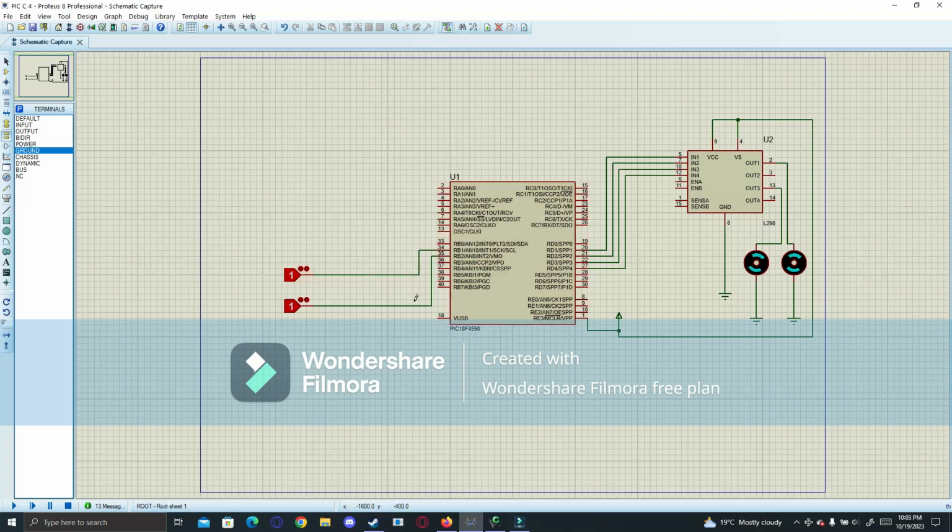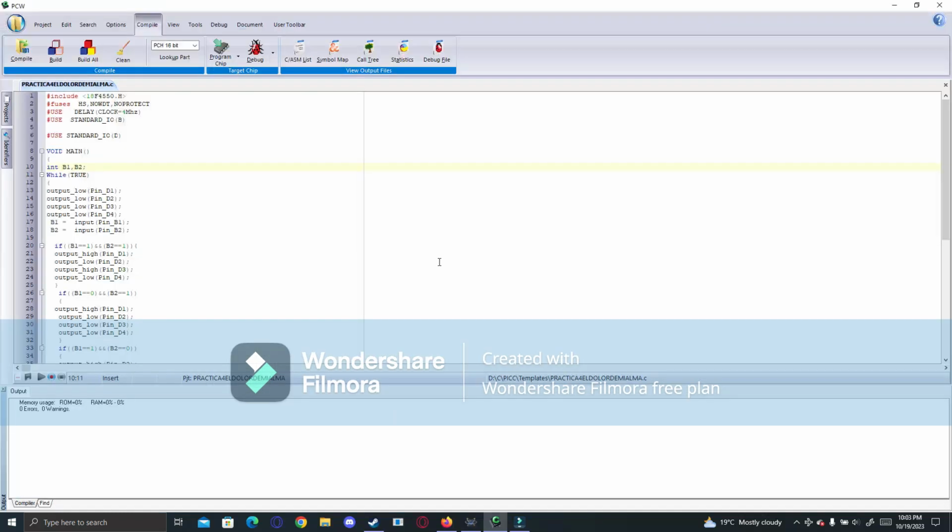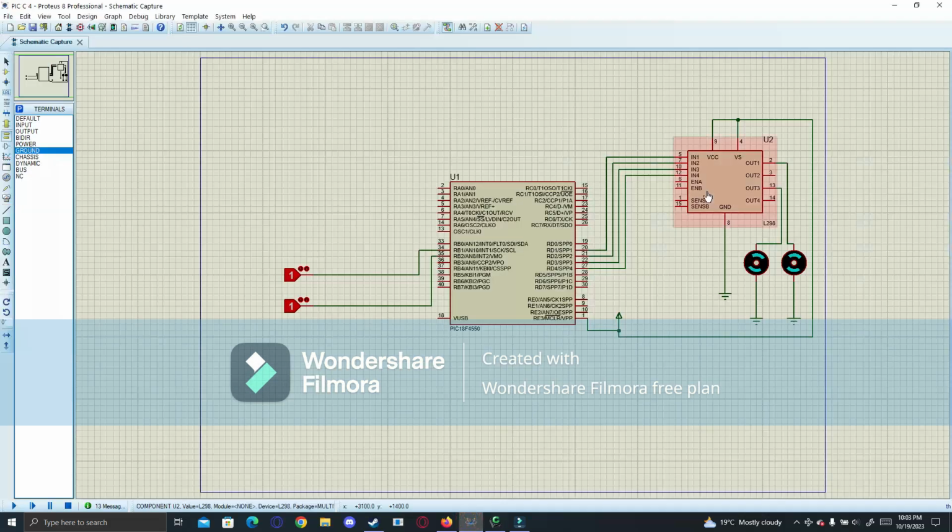The sensors will be connected to two parts of the car in the front, aligned with the motor that each is connected to. When both of the sensors are detecting no black tape, they are going to be sending a 1. This is the state they are going to be in regularly once there is no black tape, making both of the motors start to work, right?